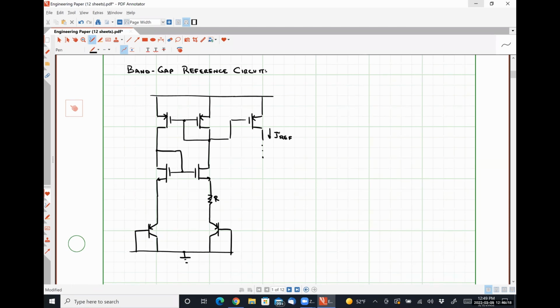So that effectively everything cancels each other out and it's extraordinarily temperature stable. It literally winds up referencing the band gap, the electrical band gap of a silicon crystal, which is constant, 1.12 electron volts, regardless of what the temperature is, which is why it's called a band gap reference circuit. Everything works out to cancel out, and the output current that's applied depends on the value of the band gap of the semiconductor that's used.